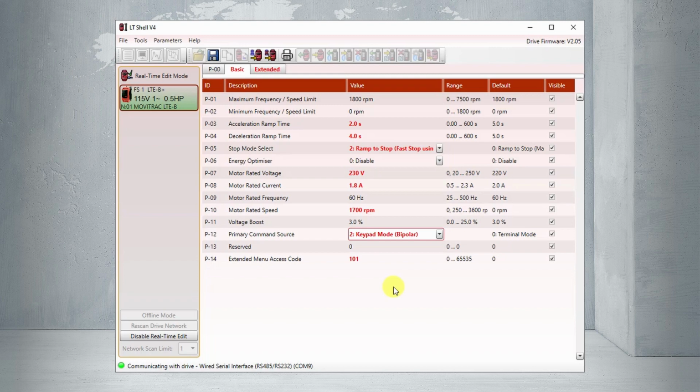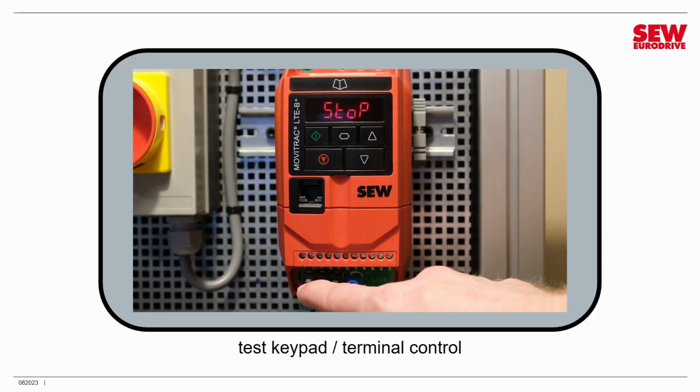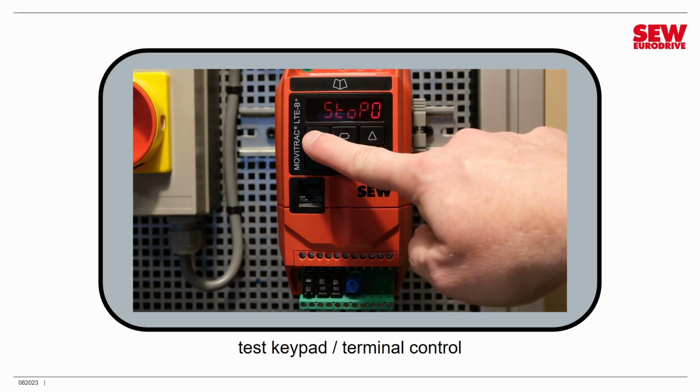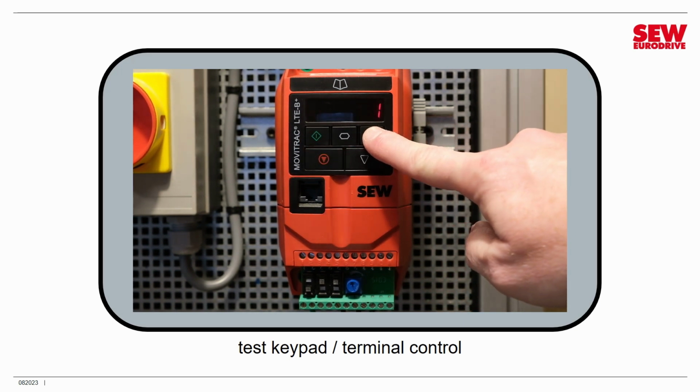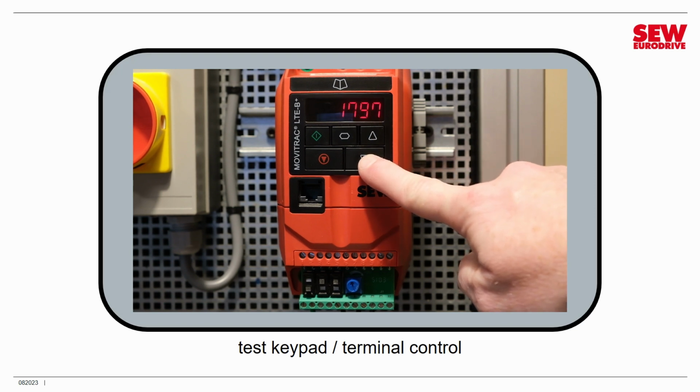Now I will be able to control my VFD using the keypad in the usual way, but I'll also have that limited terminal control mode. Let's go demonstrate that. All right, the first thing I do is enable the drive by turning DI1 on, and I press the start button on the keypad, and I'm going to just speed it up the conventional way you do with the keypad with the up arrow. We've done this before. And I'll slow it down with the down arrow. This is familiar ground.